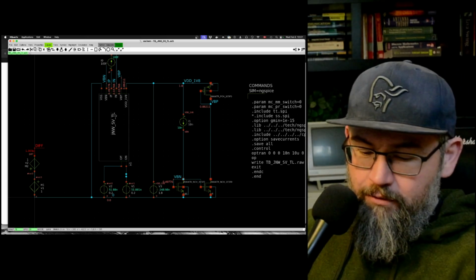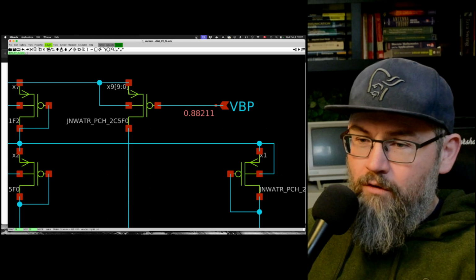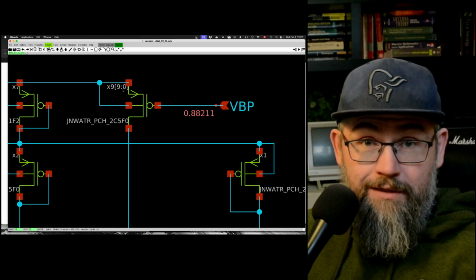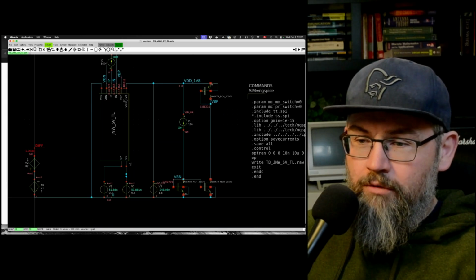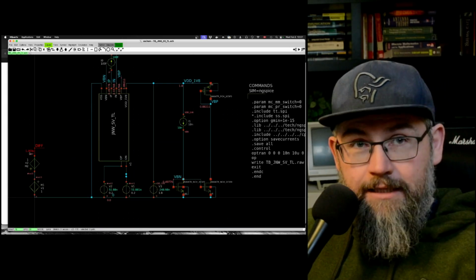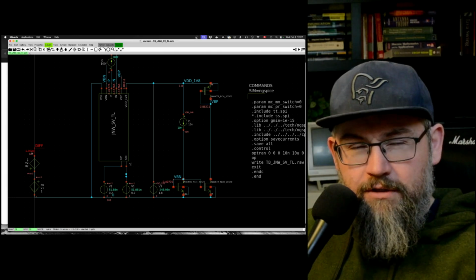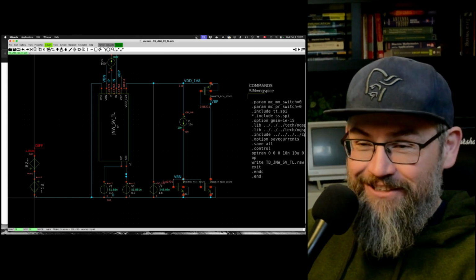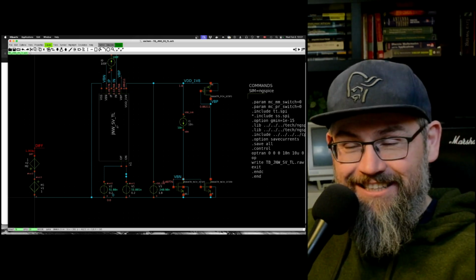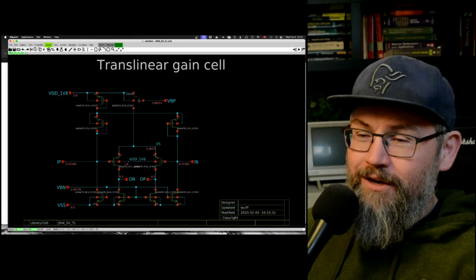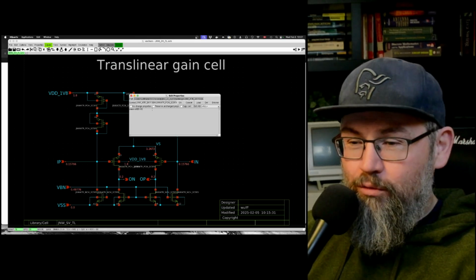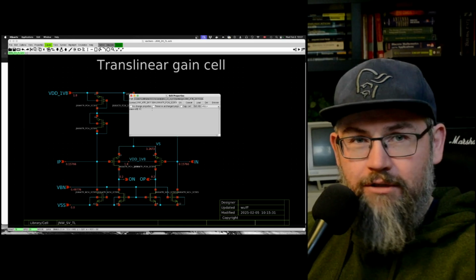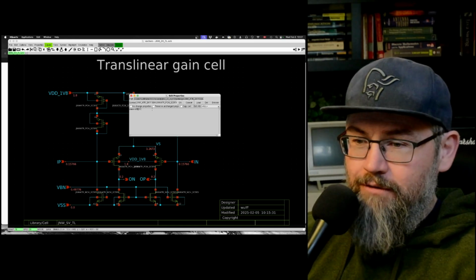Okay, so if I go inside here, I can notice that for the IB current, I now use 10 transistors. So it's natural that I actually get a factor of about 10. Now, notice it's not exactly 10, because analog, come on, there are going to be inaccuracies in here, especially at these current levels. But you can see that if I control the number of transistors, so a digitally controlled transistor, that's just a transistor and a few, or many transistors and a few switches.